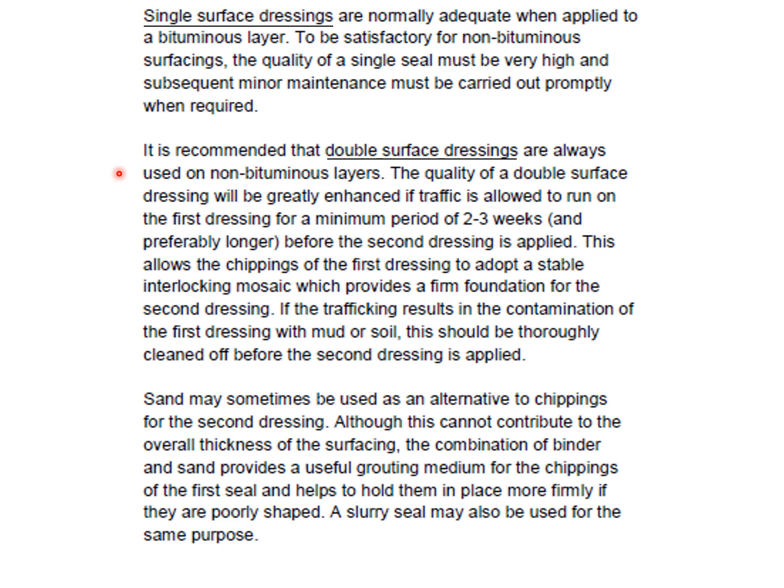The quality of a double surface dressing will be greatly enhanced if traffic is allowed to run on the first dressing for a minimum period of 2 to 3 weeks and preferably longer before the second dressing is applied. This allows the chipping of the first dressing to adopt a stable interlocking mosaic which provides a firm foundation for the second dressing. If the trafficking results in the contamination of the first dressing with mud or soil, this should be thoroughly cleaned off before the second dressing is applied.